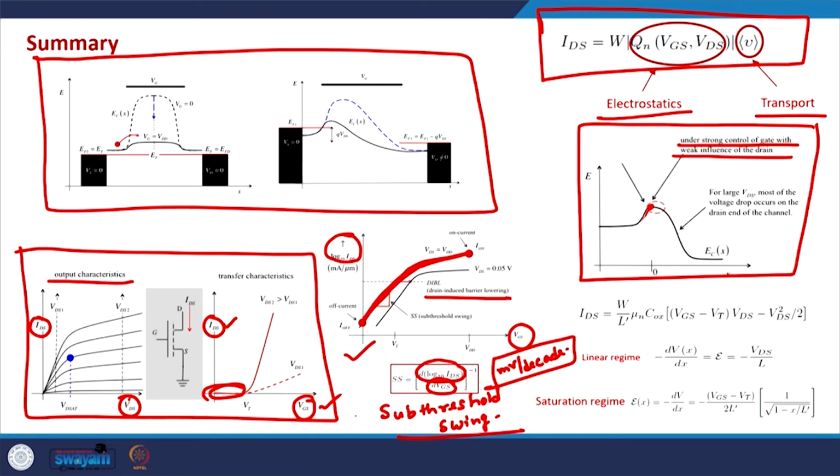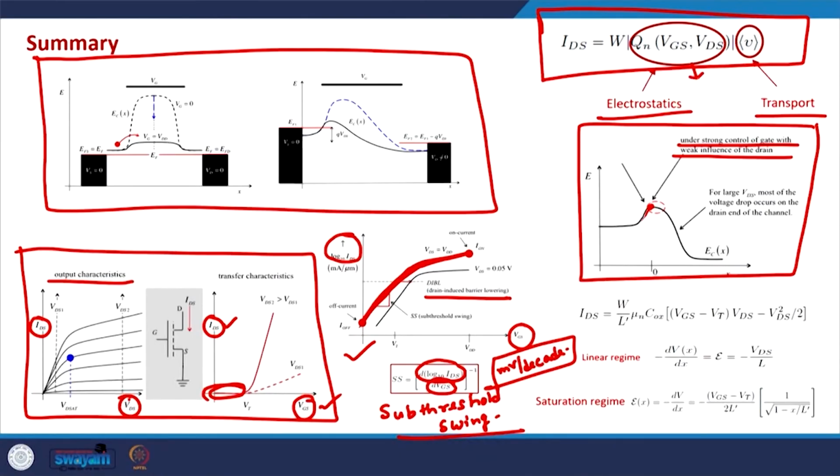Apart from this, we analyzed the current in the MOSFET in terms of the flux of electrons going from the source side to the drain side and from the drain side to the source side. But that analysis is still not complete, because in that analysis we did not put the expression of the charge explicitly and also the velocity explicitly.